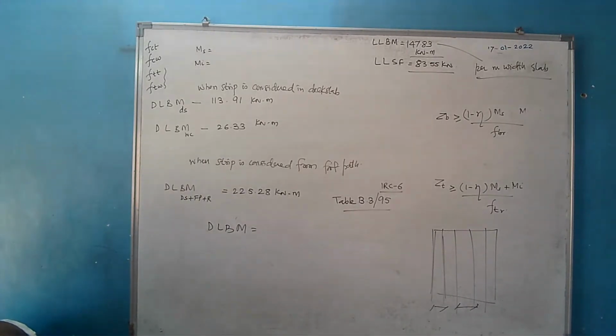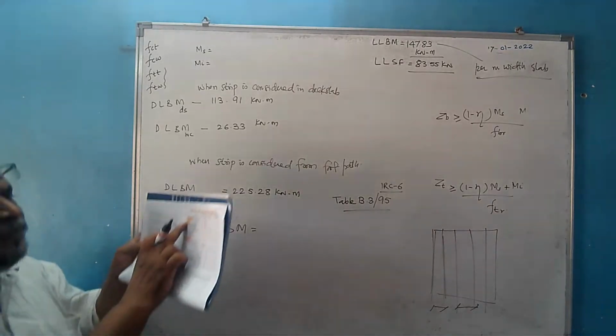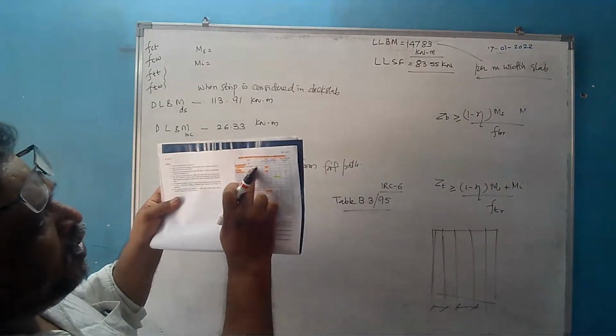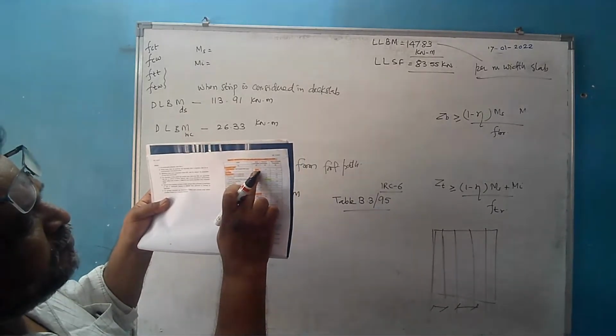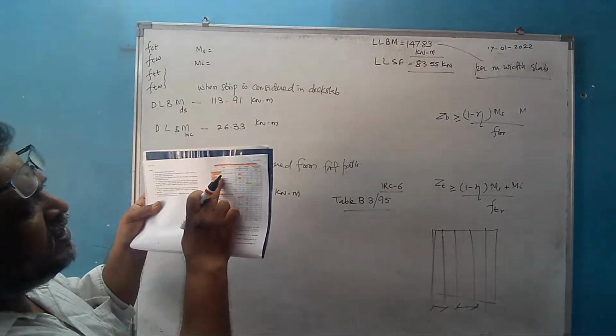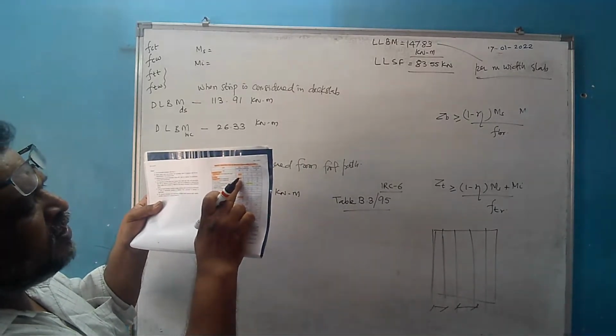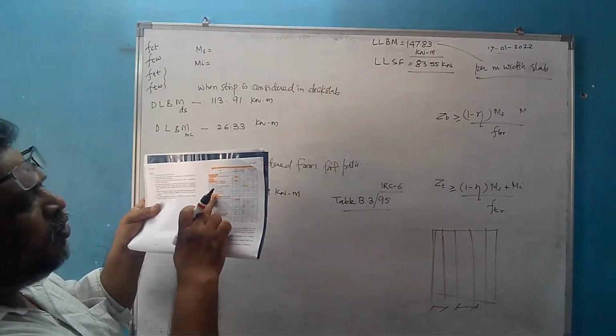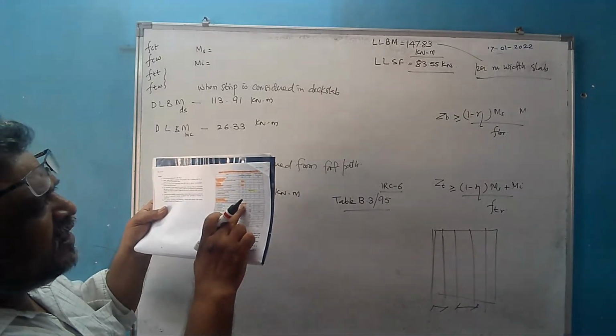तो partial safety factor for load हमने कितना लेना चाहिए? What must be the partial safety factor for load? इसमें अगर हम ये very first देखते हैं, it is permanent load. So in that case we have to consider as 1. For surfacing we have to consider 1.2. Variable loads, that is for the live load, it is to be considered as 1.